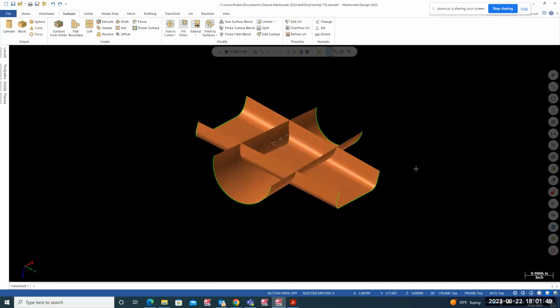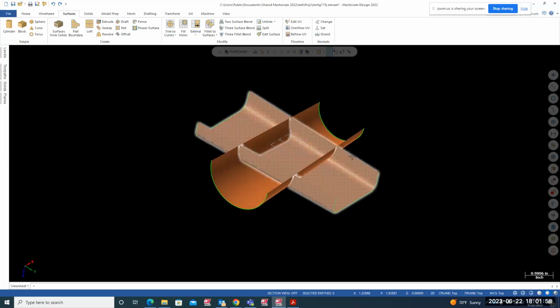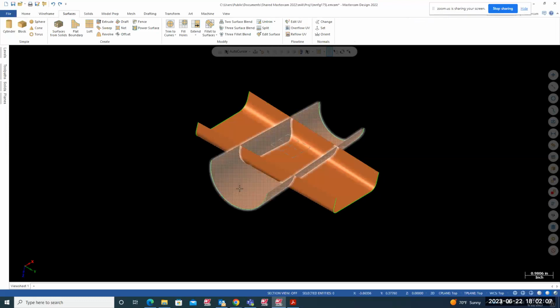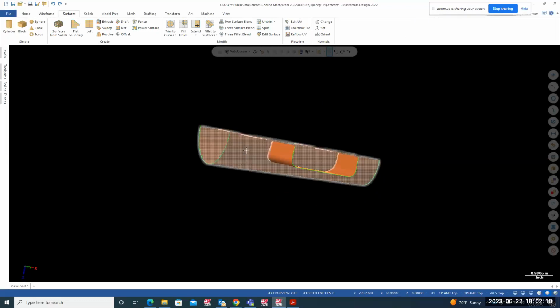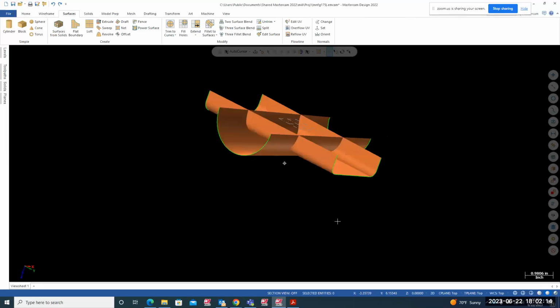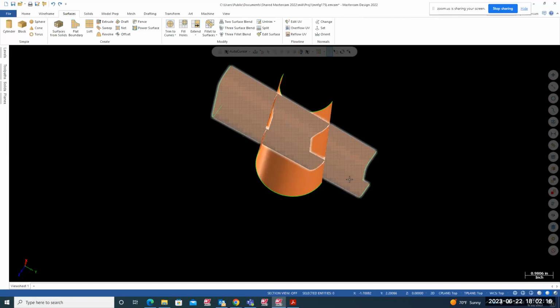And it will get rid of the stuff when it's two surfaces that are intersecting each other. What is the common, we're going to delete that. That's what it is. So when they're intersecting each other, you want to get rid of this area. So make sure you select your arrow when you select the first set. So you select this side here because you want to get rid of this. And the second set, make sure you select the outside and you want to get rid of this. So you always select the side you want to keep.